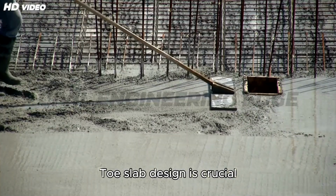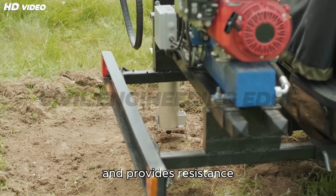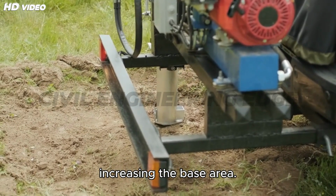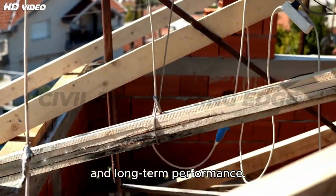Toe slab design is crucial for the stability of the entire retaining wall. It helps reduce overturning and provides resistance against sliding by increasing the base area. Proper reinforcement anchorage and detailing ensure structural safety and long-term performance.